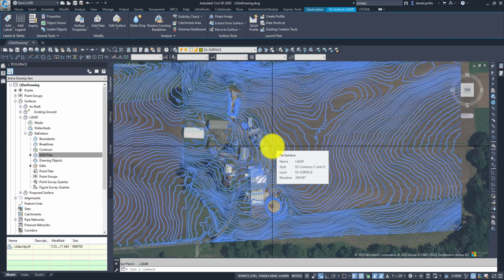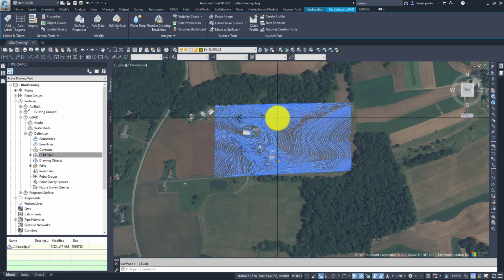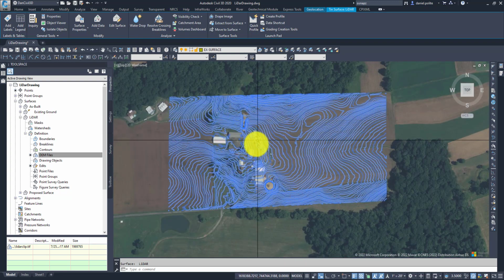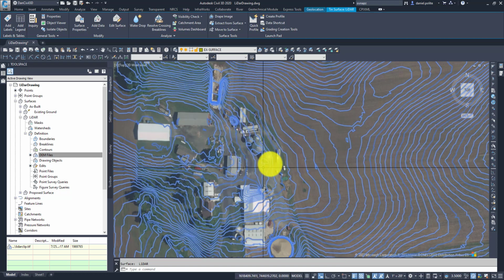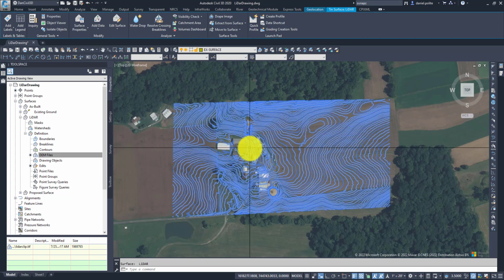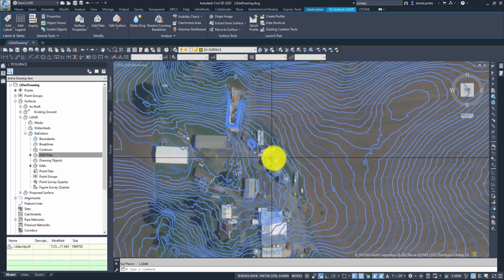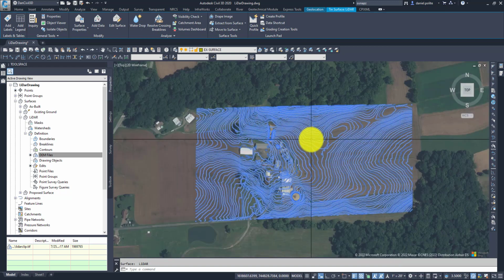If it's not crashing, then I would recommend just keeping it the same way it is, as long as you don't get such a large area. I've just seen sometimes where when you bring in LiDAR, if you're concentrating in this area right here that you're doing the design, just limit your LiDAR for that design to that area. But in this case, this was a surveyed area that we've done, and the area engineer was asking for additional topography outside of that to make sure that water was not coming into the area that we were designing the specific BMP at.